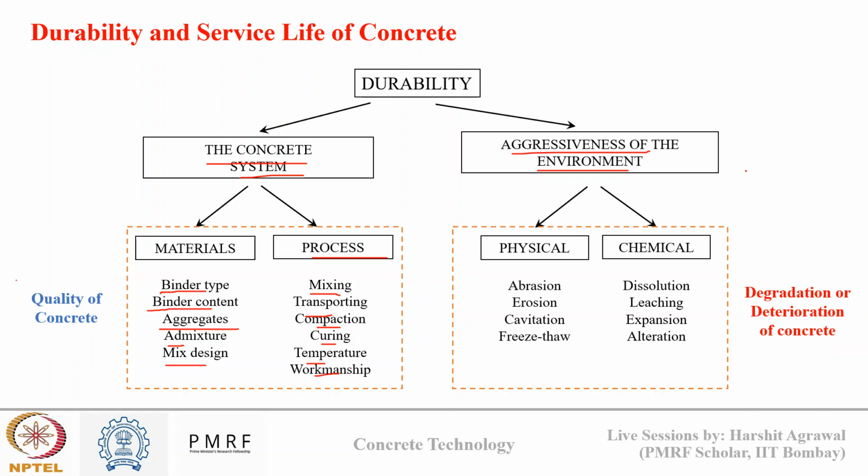And the aggressiveness of the environment decides the degradation or deterioration of concrete, which can be either physical due to abrasion, erosion, cavitation, or freeze thaw, or it can be chemical due to dissolution, leaching, expansion, and alteration. So I have both quality of concrete as well as the degradation or deterioration of concrete, which both will affect the durability of concrete.